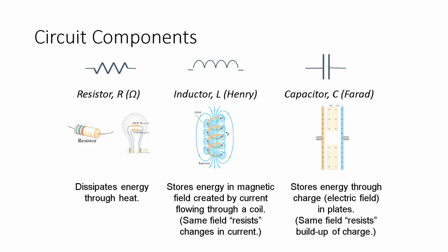So a very common place to see a resistor that we'll do in lab is putting in the correct size of resistor, the correct resistance, in order to protect an LED so that we do not burn the LED out. Because most LEDs, if you let 9 volts go through from a 9-volt battery, your LED is going to go really bright for about 2 seconds and then burn out immediately. And that's undesirable because you want an LED that lasts a long time, not one that glows brightly for 2 seconds and is done. So a resistor is a way of taking some of that extra power that's generated from the 9-volt battery out of the system to essentially protect the LED and let the correct amount of power through the LED for optimal lighting.